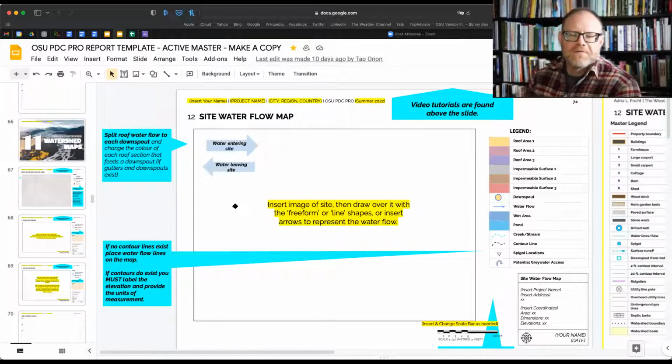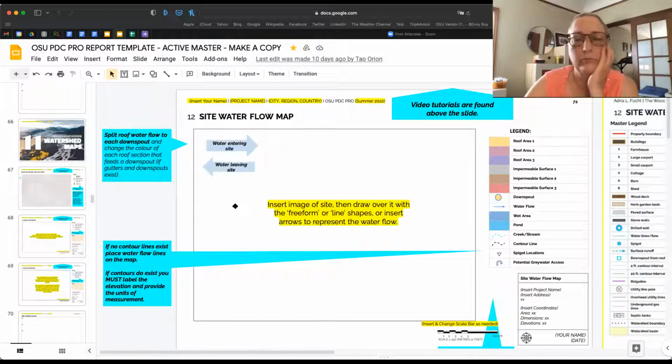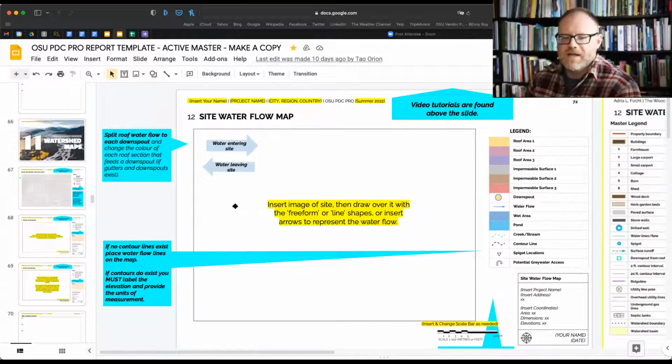So first and foremost, when I'm working in a region, I will Google search topographic or GIS and the name of that area. So if there's a county name, if there's a municipal name, if there's a rural area name, I'll type that in. That data is going to usually be at survey level or higher and give us information that we can use.